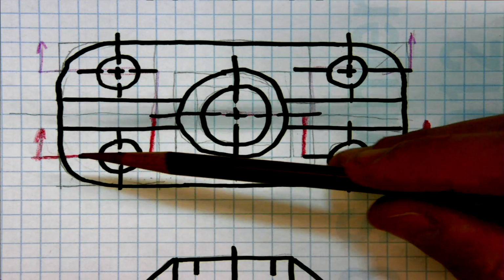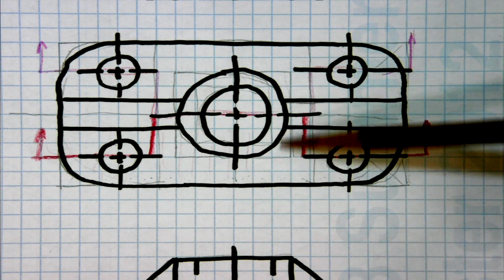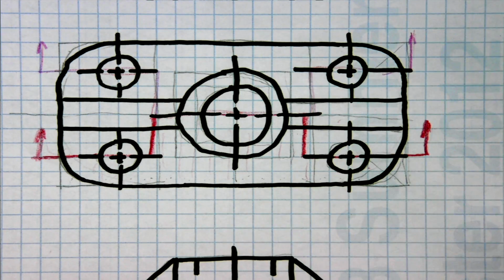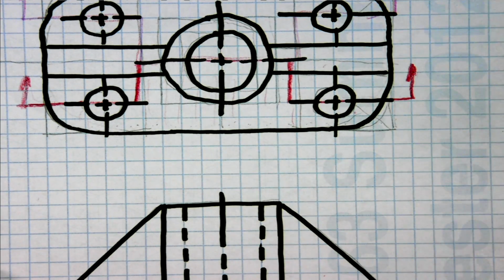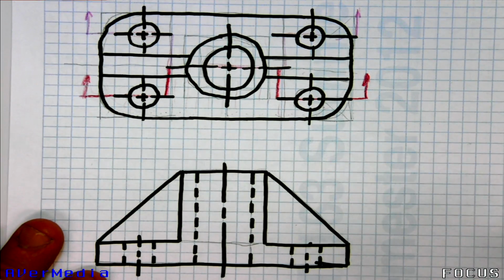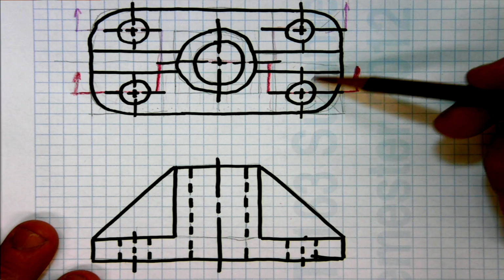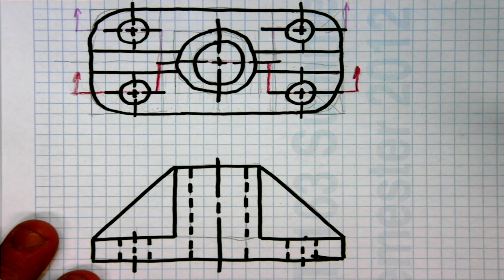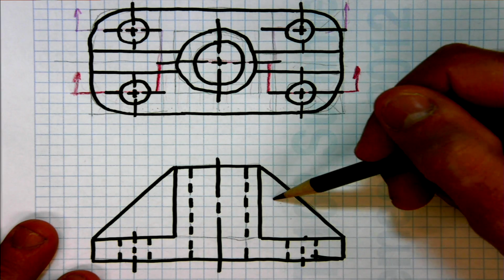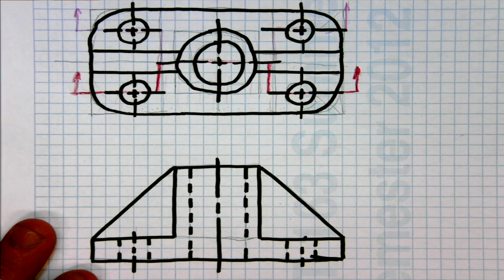So again, on this example, notice that all this area here would be removed from the object. Thus, you would keep these support features. Now, I'll scoot this up just a little bit. You would keep the support feature here because it hasn't been cut off. If we go to the back example and we cut through here, then this support feature is going to be removed. So you want to think about where you want to put these cutting planes before you go through it.